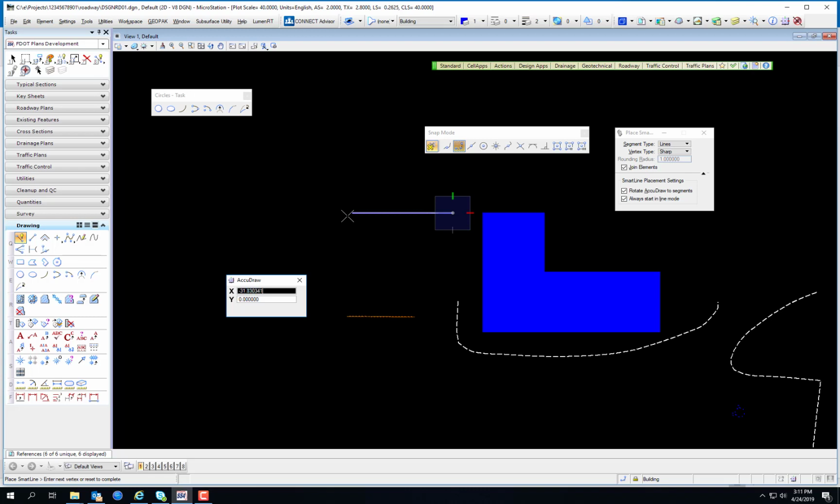But of course you can change the line. It just gives you a little snap to that distance right there because it remembers. I did point out that it does stick to the points on the compass at the 90-degree angles. If you want to lock that, just simply strike Enter, and now it is stuck on the x-axis. Strike Enter again to unlock it. Strike Enter, and now it's stuck to the y-axis.